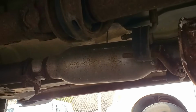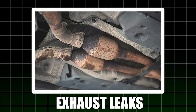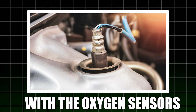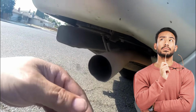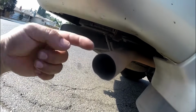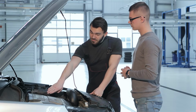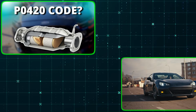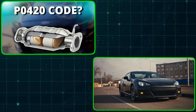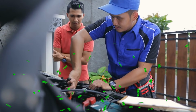Common causes of this code include a failing catalytic converter, exhaust leaks, or issues with the oxygen sensors themselves. Identifying these problems often involves inspecting the exhaust system for leaks, testing the oxygen sensors for proper functionality, and checking for any other related engine issues. Addressing the P0420 code promptly is essential to ensure your vehicle runs efficiently and remains compliant with emissions regulations.